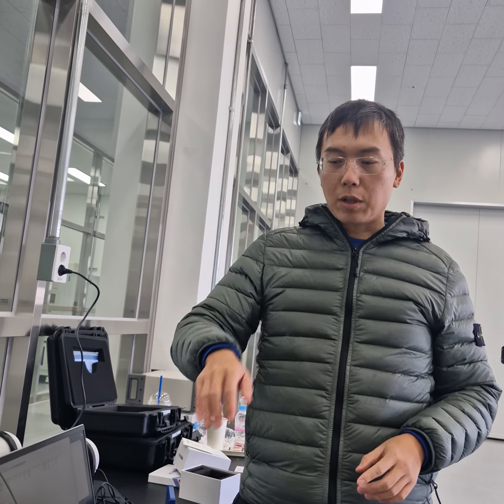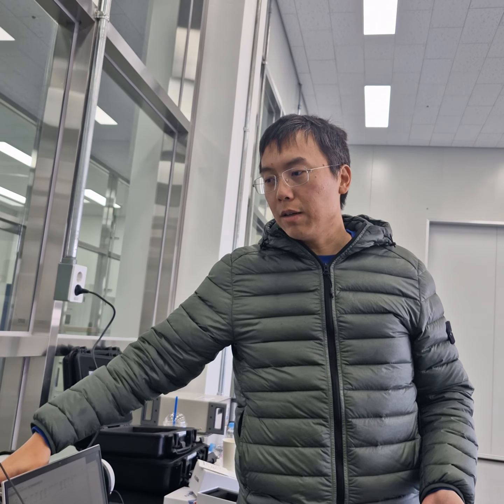So I would say the calibration will be more important if you are doing sound measurement, like you're testing that machine. Okay. So it will give you the absolute value of what you are testing. But in the sound transmission loss and sound absorption test, in the equation, in the end the amplitude will cancel itself, because the final result, absorption and transmission loss, is just a ratio.